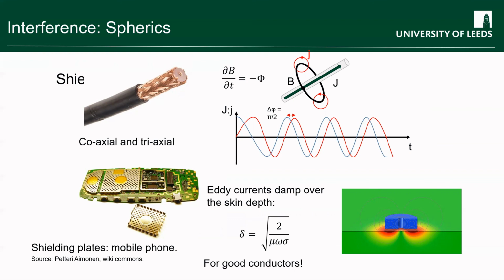And then of course inside your room you have to be very careful you're not introducing any noise sources, so you make sure you leave your mobile phones outside, but also you run all the equipment inside it off battery packs, so that you don't have a 50 hertz mains signal. Everything is being run directly from DC batteries.